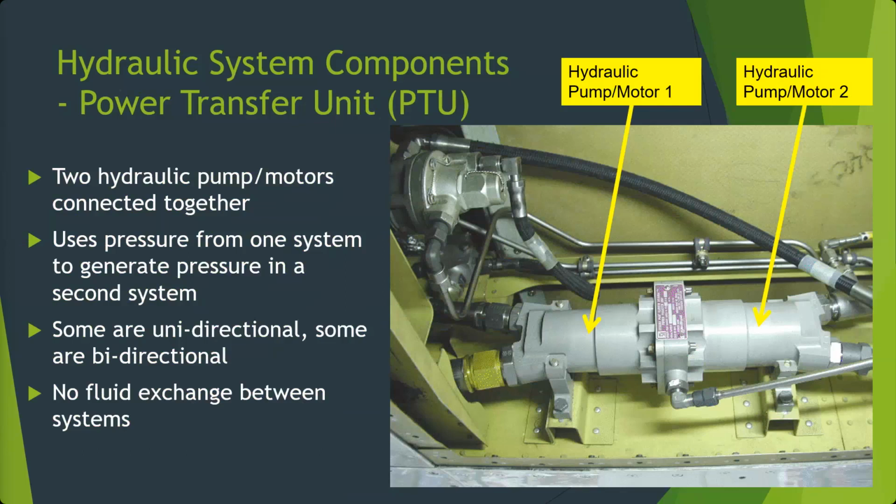The one difference is that the swash plate is in a fixed position. They're not variable. So they have a fixed angle of inclination, and you send fluid in one side, that pushes the pistons, causes it to spin, and fluid comes out the other side. And that rotating motion can then be used to drive something. So we take a hydraulic motor and we drive something else.